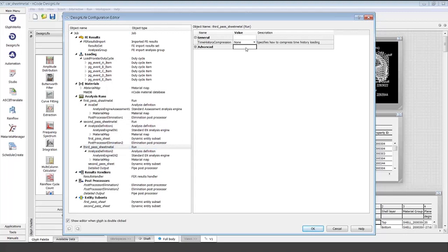The beauty of this is, since we're only analyzing 1,000 remaining high damage, high stress elements, we can do some really complicated, fully featured fatigue stuff here and still have a reasonable amount of time. What we don't want to do is use a fully featured, computationally intensive fatigue analysis method on the entire model, or even a large portion of the model, because that's calculation time.